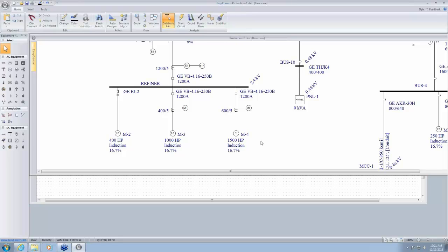And later, after the 1584 standard was published, there were some other engineers that pointed out, if you have a horizontal configuration, the arc can come out towards you and much closer to the worker. And in such cases, the incident energy can be significantly higher.